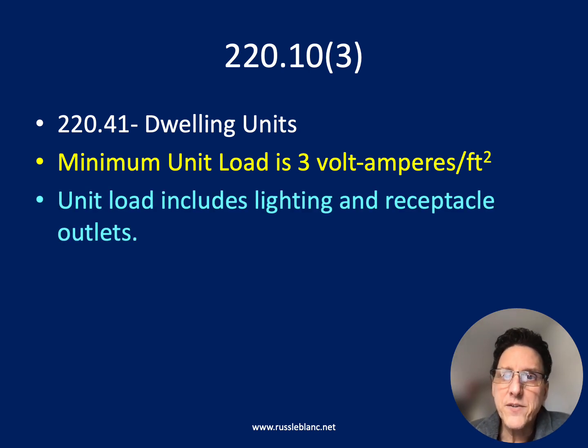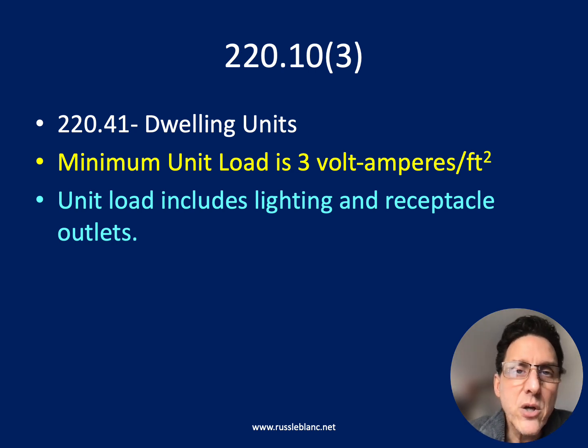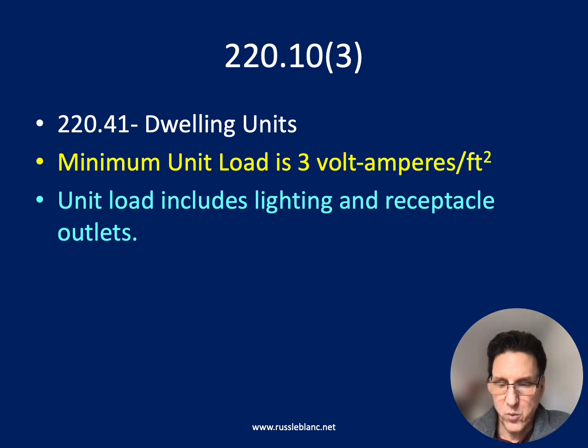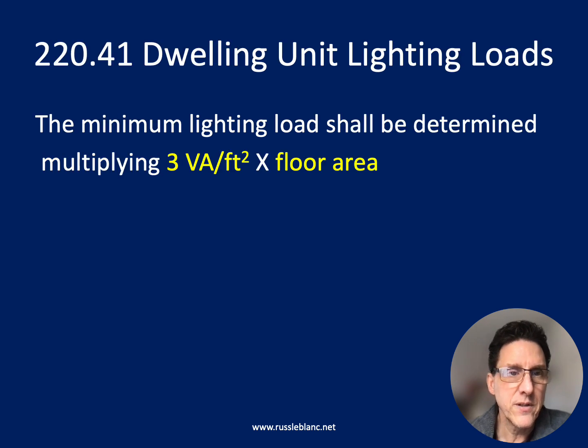And it also says in 220.41 that the unit load includes the following: lighting and receptacle loads. No additional load calculations are required. And we're going to look at the specific wording there. But generally speaking, all the lighting and receptacle outlets are included.